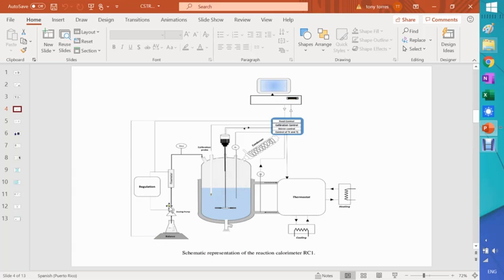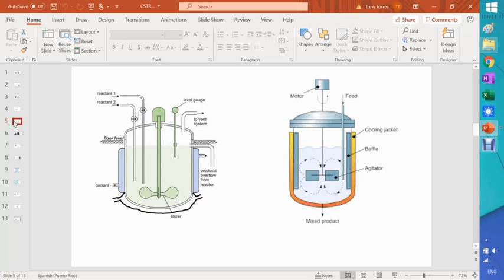Like, for example, during an addition of reactant to something that is already here, that will generate some heat, and you have to remove that heat. So you want to be sure that you have the proper UA factor at your plant facility, because this is sort of a scale down of what you are doing at the production level. Okay, and this is computerized, which is great.